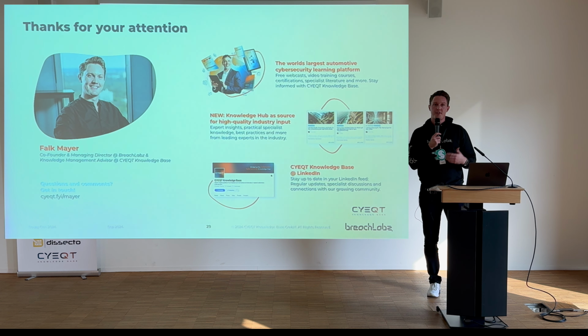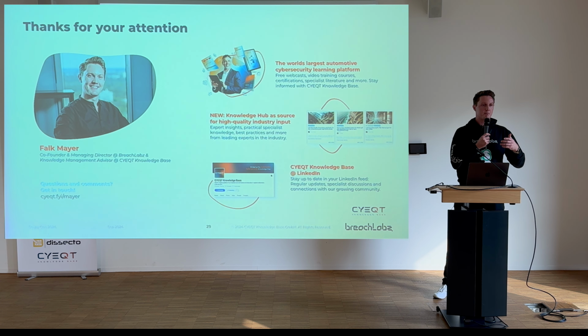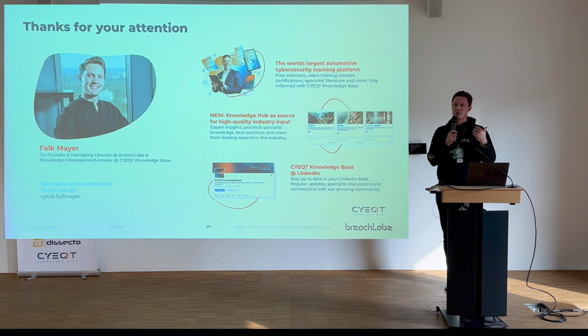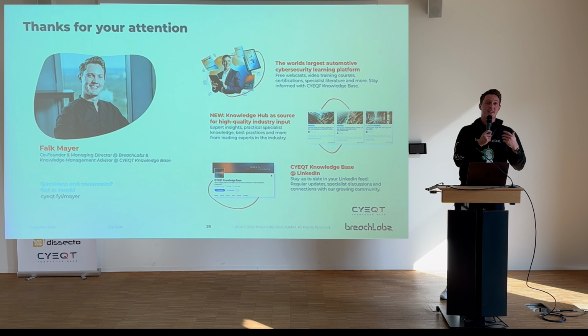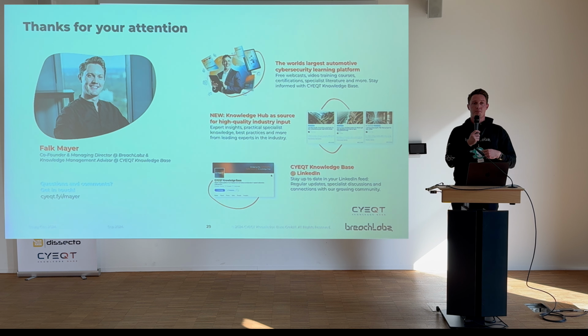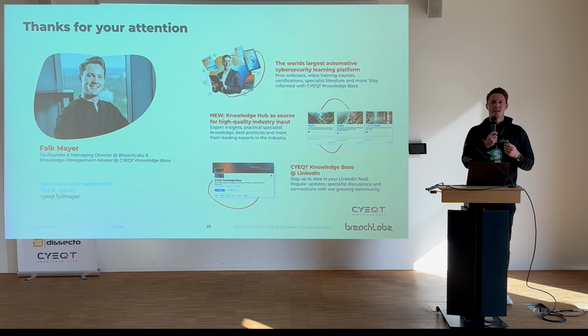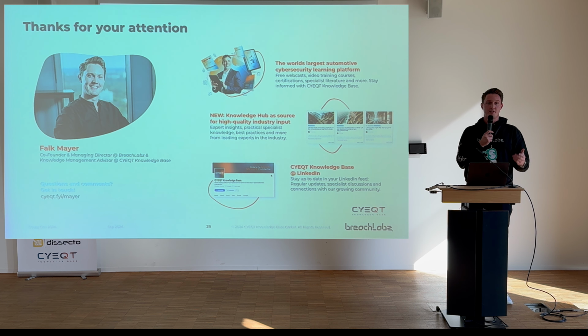And the second thing is basically also based on the same mechanism. Usually when the device boots up, for example, on ARM architecture, there's a certain register, sort of a flag, that says whether the debug interface should be locked, right? And this is where the beauty of fault injection again comes in. If you are able to determine the exact timing after boot, this is how you can then bypass, for example, that this register is correctly set.